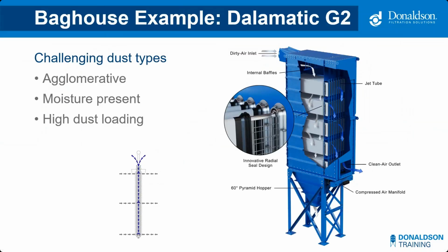Okay, I mentioned that there are pharmaceutical dusts that can be hygroscopic. They attract moisture, and that sticky, moist dust can be very challenging because it cakes on the filters and it dries, and then they become less breathable, right? In these types of situations, we look to more of a specialty style baghouse collector.